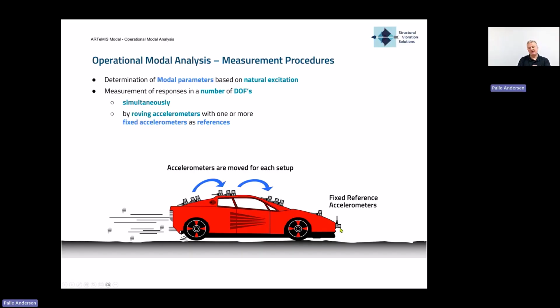And based on that, we can now extract a mode shape piece every time for these 2 sensors here. And that mode shape piece should be the same for all these 3 measurements that we have been doing in this case here. But they are probably not, because if you have a vibration level that suddenly raises or falls from one measurement to another one, these mode shape parts here will not be the same. They will also change level.